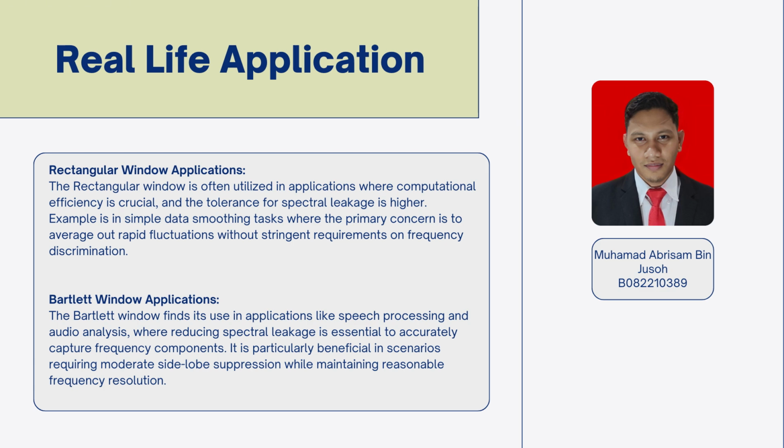Okay, second, the Bartlett window application. The Bartlett window finds its use in applications like speech processing and audio analysis, where reducing spectral leakage is essential to accurately capture frequency components. It is particularly beneficial in scenarios requiring moderate side-lobe suppression while maintaining reasonable frequency resolution.